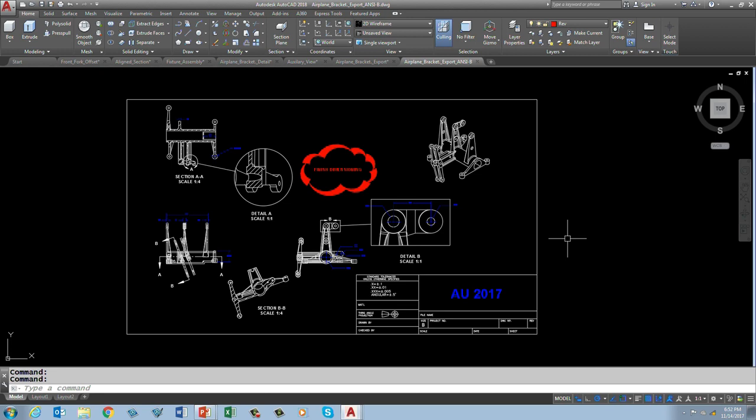Look at number 1. See that line that comes down where I make the jog of the section line? That's technically incorrect. That should not be there. You cannot delete that in AutoCAD. It's a gotcha. Autodesk Inventor used to do that years ago. Had the same problem for many years.